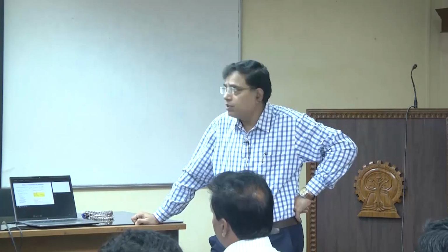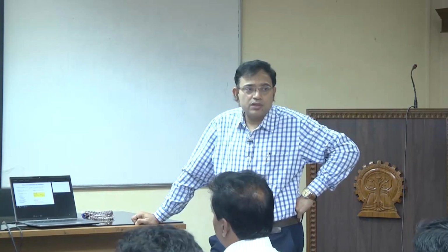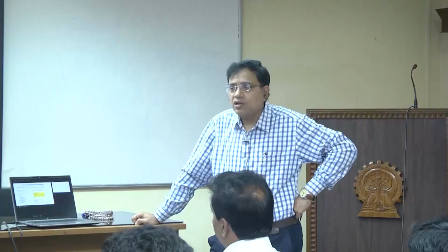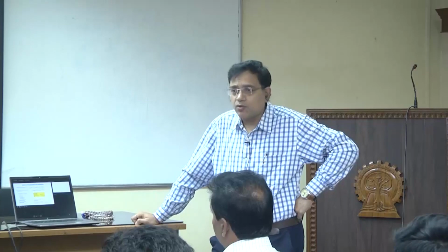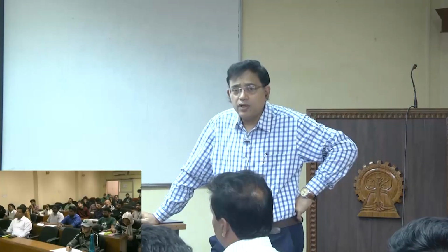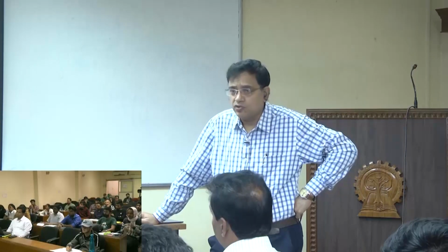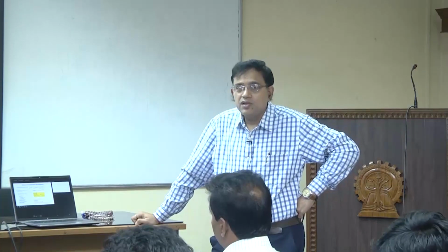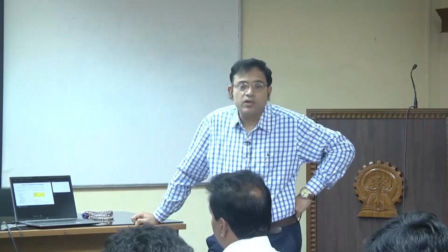Now, to solve that problem, you have to keep in mind what the temperature is now, and say we are going to work out the temperatures at subsequent times. We cannot influence what the temperature was 1 hour back, right. Whatever was 1 hour back was 1 hour back. We can influence only what is going to happen from now, going forward in time. So, this is called a time marching problem. This time marching problem is technically a parabolic problem. That means you have a one way coordinate system.